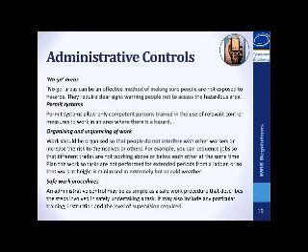Relevant information and instruction should be provided about no-go areas, with adequate supervision to ensure that no unauthorised worker enters the no-go area. Barriers should be used in conjunction with signs to cordon off areas where there is a risk of fall or being hit by falling objects. They should be highly visible and securely fixed to prevent displacement.